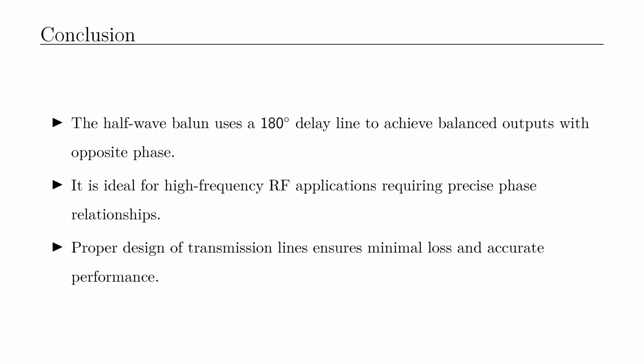In conclusion, the half-wave balun achieves balanced outputs with opposite phase using a 180-degree delay line. It is ideal for high-frequency radio frequency applications requiring precise phase relationships. Proper design and careful implementation of the transmission lines ensure minimal loss and high performance.